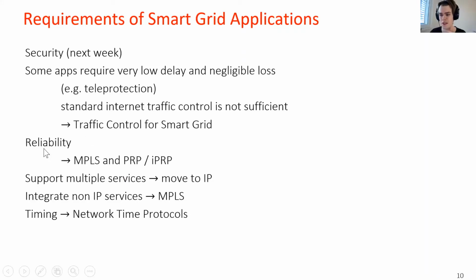I mean, isn't that part of what we did with the PMUs, where you need to agree on what happened when? Exactly. On the PMU, you measure a time shift. You measure offset of a sine wave, right? So for that, you need to have the same time in all the PMUs. If you have only one PMU, there's no problem. But typically, you want to measure not just voltage and current at one PMU, but at multiple PMUs. So you need to synchronize the time at different PMUs.